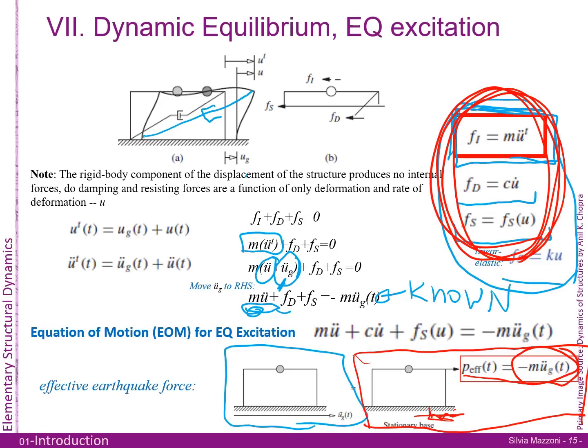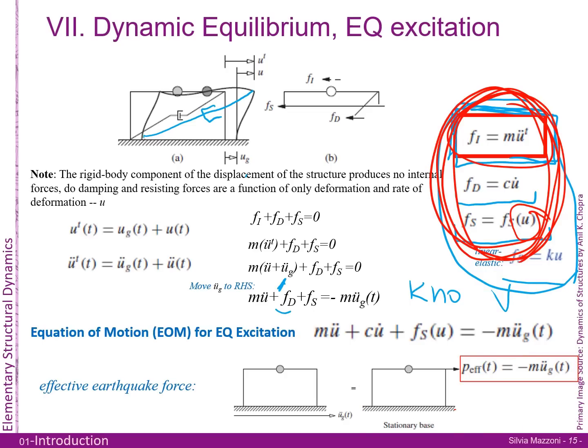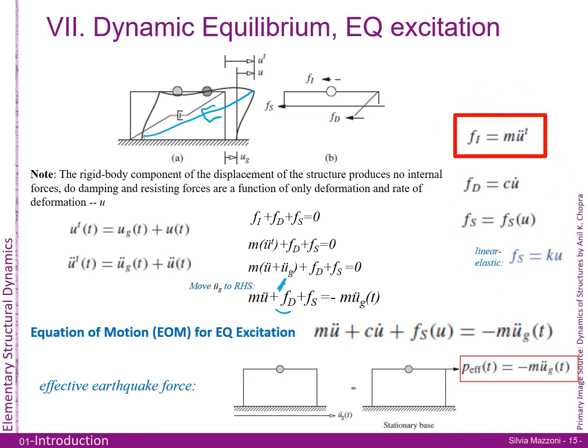And so it's interesting because when you go down the line and you start doing your analysis in OpenSees and whatever, perform or different models, the output is, hey, what do you want? Do you want your relative acceleration, which is the second derivative of this displacement, or do you want your total acceleration? And you actually have to tell it which one of the two, and they're two very different concepts. So I wanted to get this out of the way only because this is important and there's nothing hard. It's just a little tricky, and you just got to make sure you understand what we do when we've got earthquake excitation. Okay, so I want you to look at this, spend a little bit of time on this, review it, and make sure that you understand what it is that I'm doing and why I'm doing it. And this is why I spent a bit of time on this.